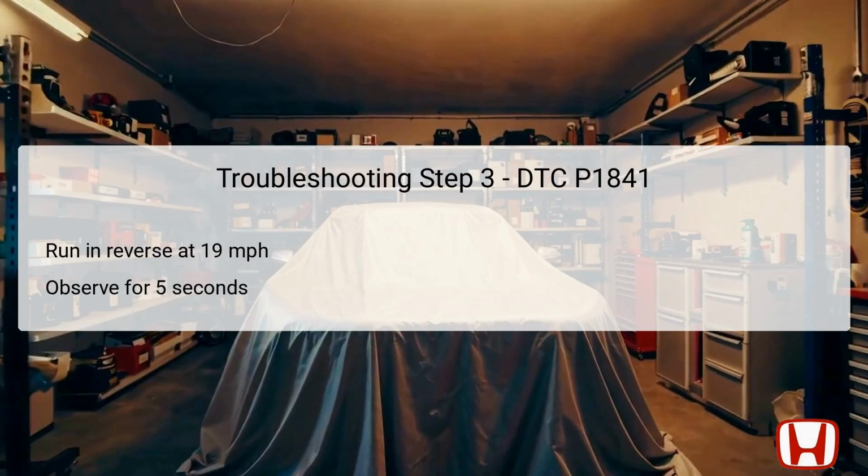During this period, it is particularly important to monitor the speed and ensure compliance with the specified parameters to achieve accurate readings. Any discrepancies in performance observed during this period can help determine if the CVT speed sensor is functioning correctly. If the sensor is operating as intended, the expected speed will be reported accurately to the TCM. If not, this could confirm a malfunction within the sensor or its associated circuitry.